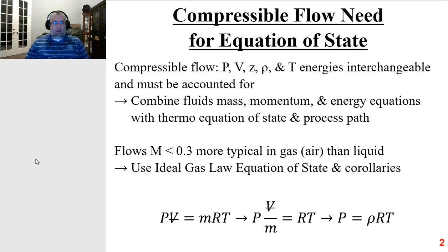And we're going to then use the ideal gas law as our equation of state. And because we're using the ideal gas law, there's a number of simplifications and corollaries that spin off from that, which I'll talk about in a little bit as we start tackling the energy equation and the process paths for compressible flow.